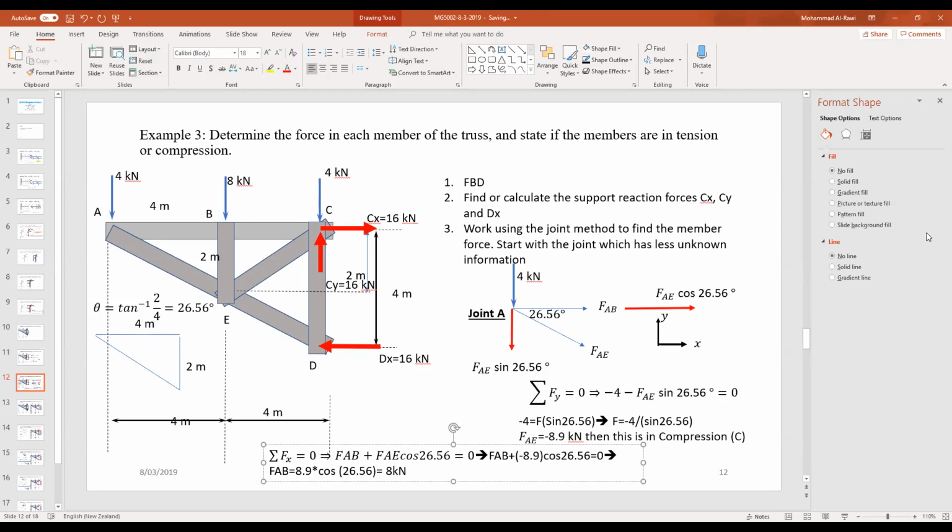So now, because I didn't change the direction of the arrow, because I'm following what I started with in my assumption, since I assumed it's going that way, but we know it's not anymore in tension, it's actually in compression, as we stated here. Therefore, I acknowledge what I assumed is wrong, so I applied the negative sign to say, hey, I'm still following my initial drawings, but I'll use the negative sign.